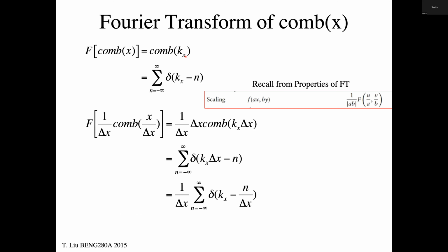If I shift the frequency slightly of the cosine with respect to the set of spikes, and I integrate out to infinity, right, that's going to be a smaller number, right? And so when you take it to its example at infinity, you can imagine that the only values in that Fourier transform that are going to give you coefficients back are going to be these discrete frequencies that have a 2 pi, 4 pi, 6 pi phase shift between the spikes, right?